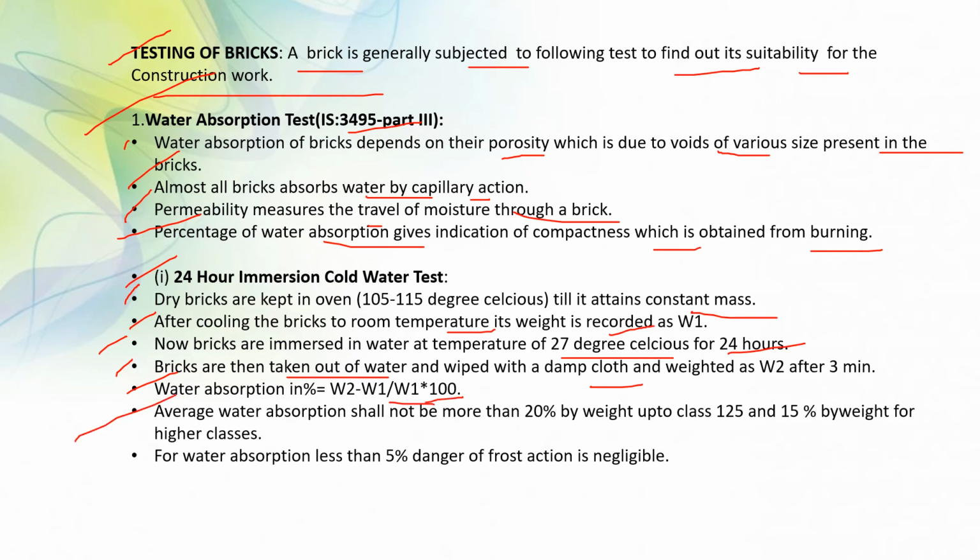Average water absorption shall not be more than 20% by weight up to the class given there. For water absorption less than 5%, danger of efflorescence is negligible.